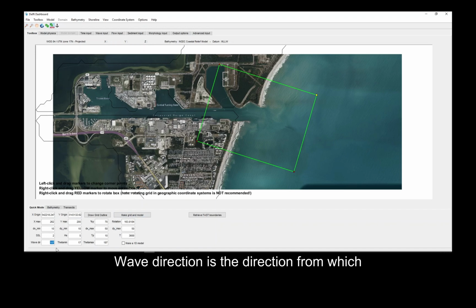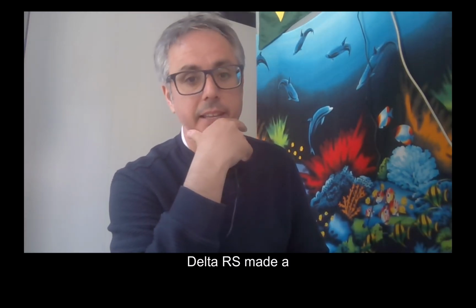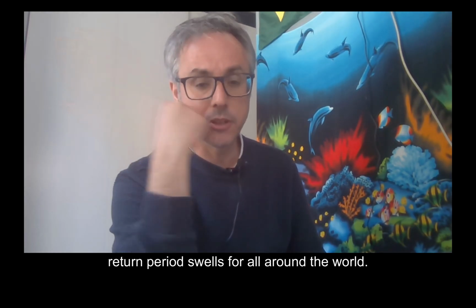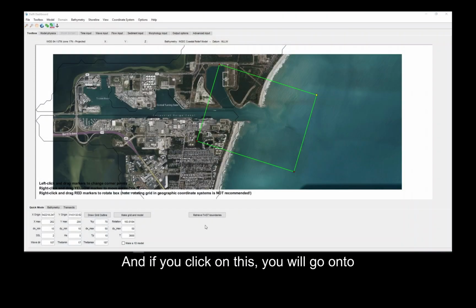Wave direction is the direction from which the waves are coming. Here you have this very interesting button, which is called Retrieve Fast Boundaries. A few years ago, Deltares made a database of 1 in 100 years return period swells for all around the world. And if you click on this, you will go onto the database and you will basically get those data. So if you click retrieve fast boundary, these values have changed.